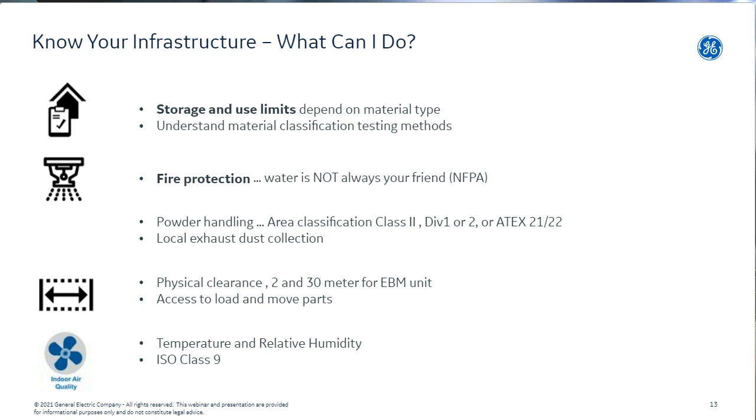Operating electron beam machines, as I already said, they generate X-rays. So there are specific clearance levels when you put these machines there, either protecting other electronic components or even from the occupational health and safety perspective. Also, the parts that you can print there, as I said, can be very small printers, can also be very large printers, and they are really on the build plate and can be very heavy. So therefore, you should understand, just from the ergonomic point of view, how to move these pieces around and how to get them out of your machine and back into the machine.